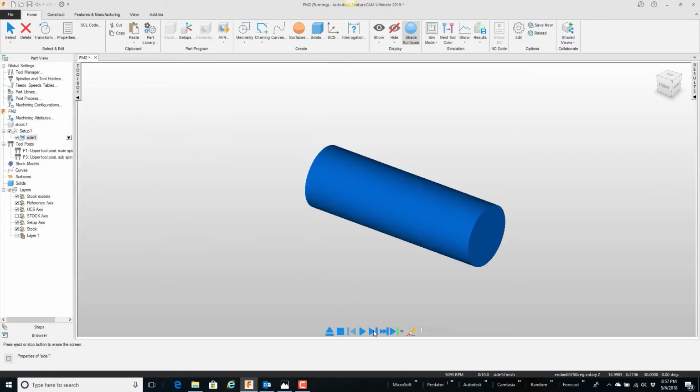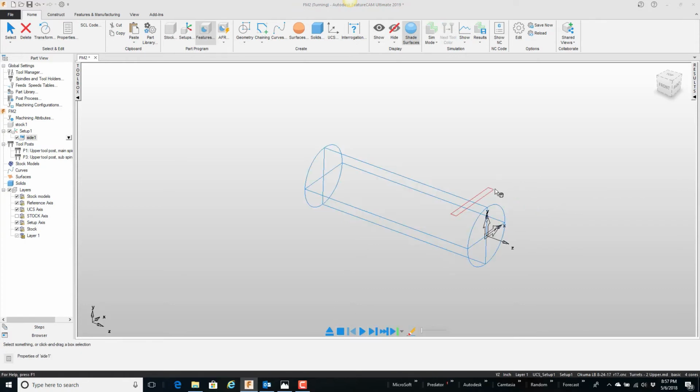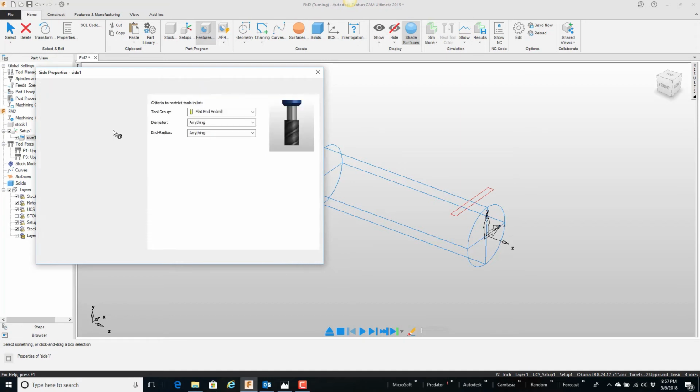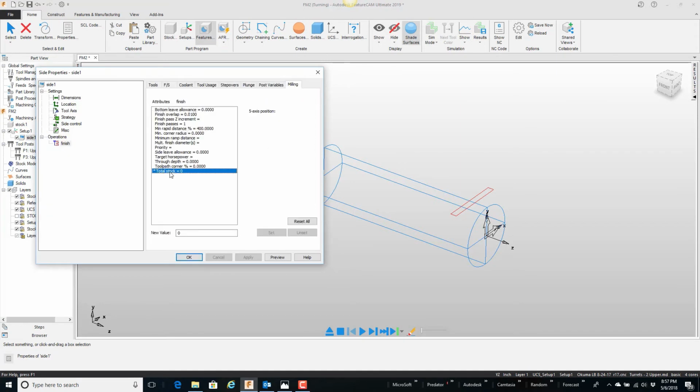If I single step, you can see the tool cut across this edge. And of course, it's using the x-axis to rotate it. But anyway, let's go back into the feature and tell it that we're going to take off that total stock.